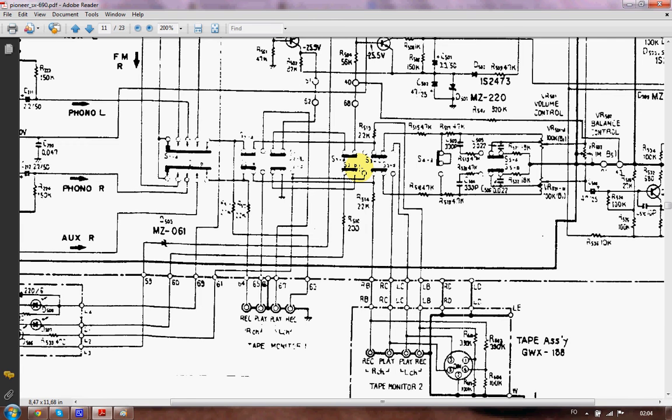And where do they disappear? First, of course, we're going to look at the speaker outputs, which they're obviously not existing in. Then we're looking at the main amplifier input. Then we're looking further back to the preamplifiers, their input. And if they don't have an input, we look even further back to see where it enters the amplifier circuit, and that's from the tuner circuit, or if we have a guitar, from the guitar's input wire.